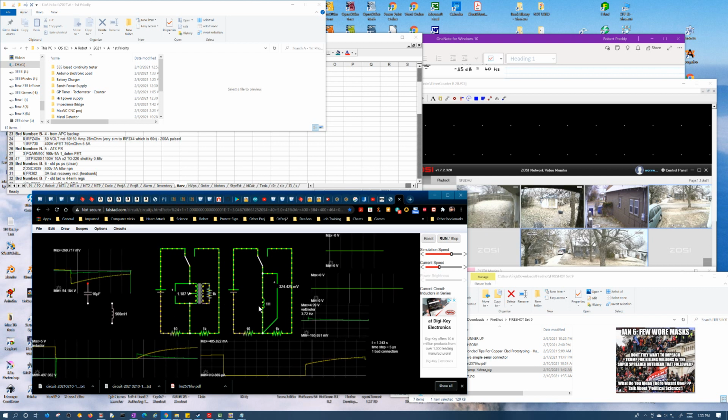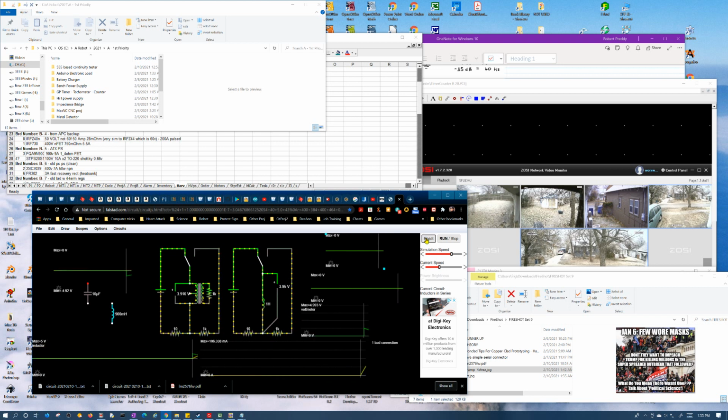So at any rate, let's go up to 1K on this. Reset it. At 1K, these things are actually pretty similar to each other, because that is such a very small load here. I mean, it's just a milliamp or so. So that's 4 volts across the resistor here. This had 4 volts here. And the charging times are similar because the resistor has less impact because it's a large impedance.